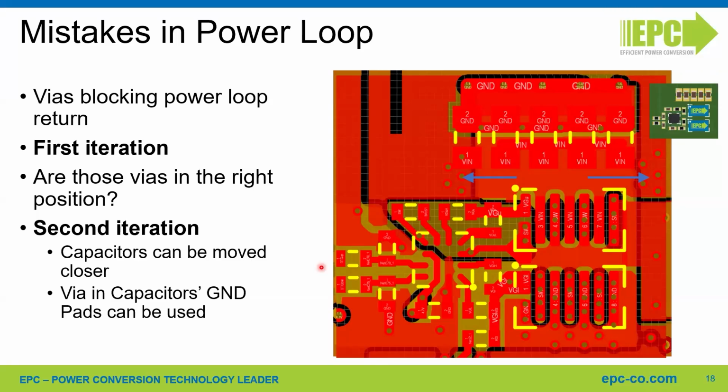No, if you use one gate driver for each FET, you have a chance of mismatch in propagation delays between the several gate drivers, and that is not helping to equalize the losses during switching. So the best option is to use a single gate driver driving all the parallel FETs.